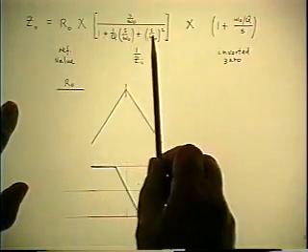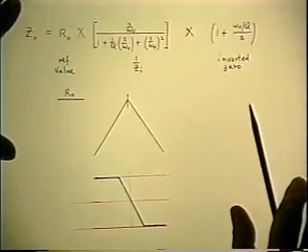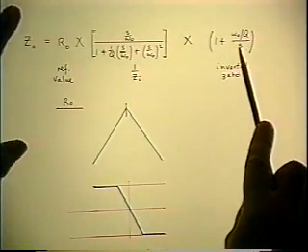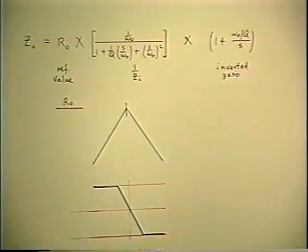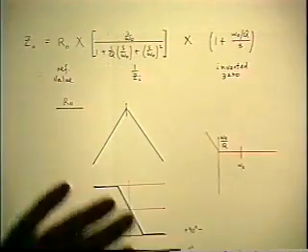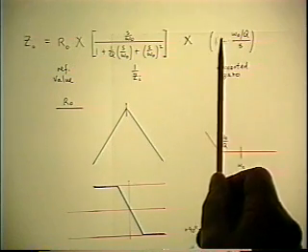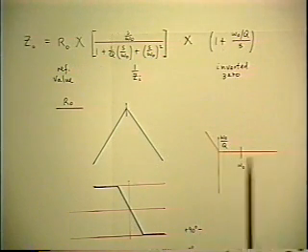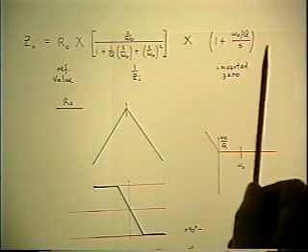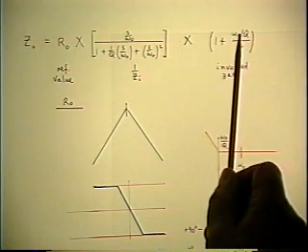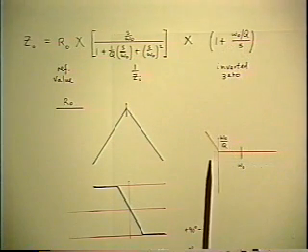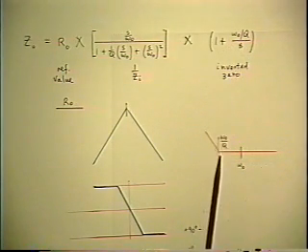So that takes care of the first two terms, and all I have to do is put the third term in. That's an inverted 0. So this means at infinite frequency the magnitude is 1, 0 dB, and as I come down in frequency, at the frequency omega 0 over Q, there'll be a concave upwards corner.